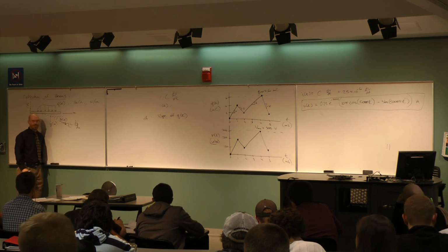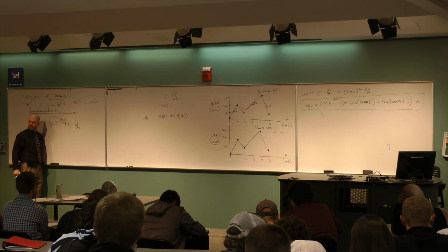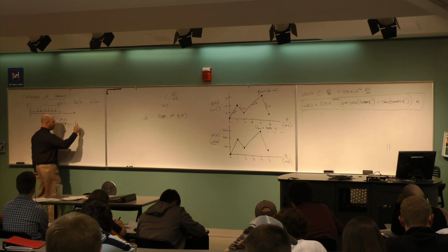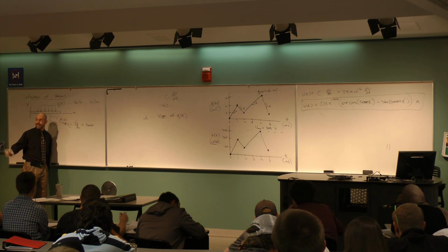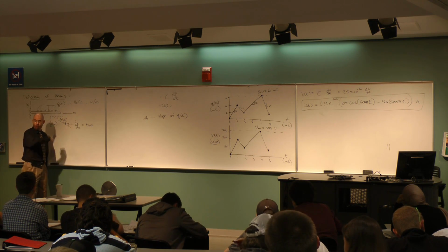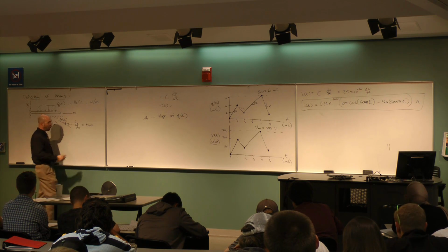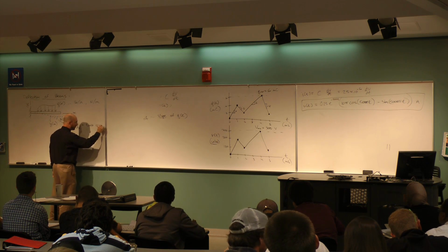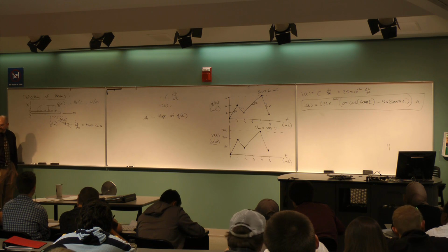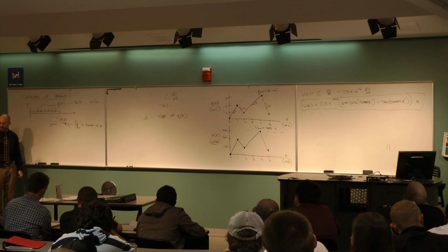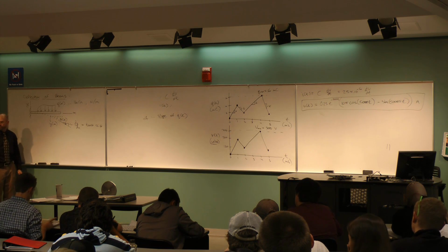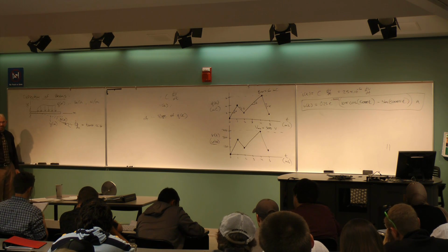If this is 1, then the vertical is dy dx, which is equal to the tangent of theta, no matter how big theta is. But for typical small angles, this is basically the same as theta. Even at 5 degrees, where I can see the deformation with the naked eye, to 3 digits I get the same answer for theta and tan theta.